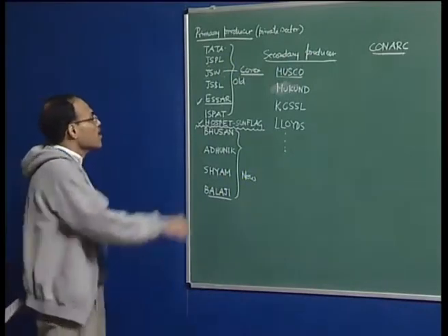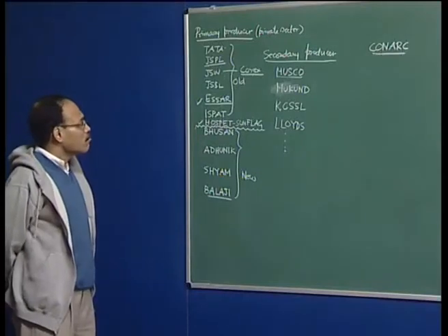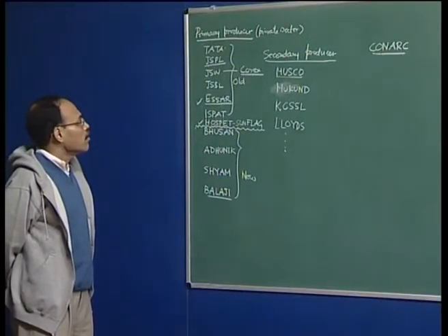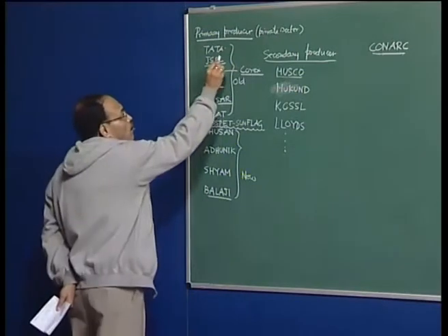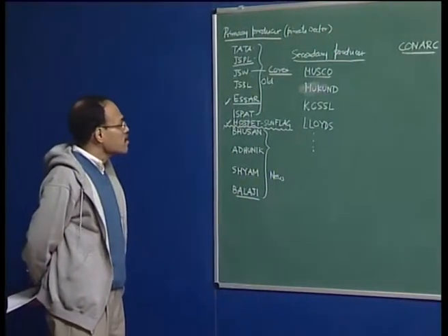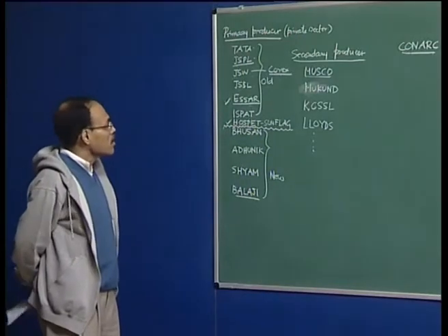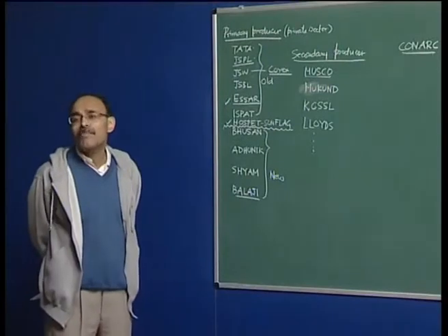If you go to JSPL, they have both electric arc furnace as well as liquid metal production units like blast furnaces. They have also bloom casting, near net shape casting as well as slab casting facilities. So they produce both flat products as well as long products. JSW at Toranagallu is a flat product plant. They don't have billet or bloom casting.